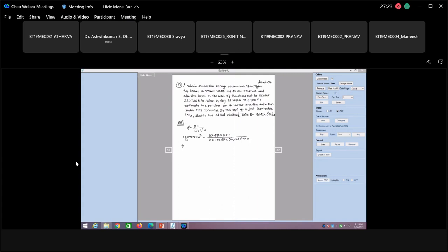This comes out to be 4. Okay, n comes out to be 4. I go by the value which you people have given. That is correct. Now, what is the expression for delta? For delta, we use F L square divided by 4 modulus of elasticity into thickness T.